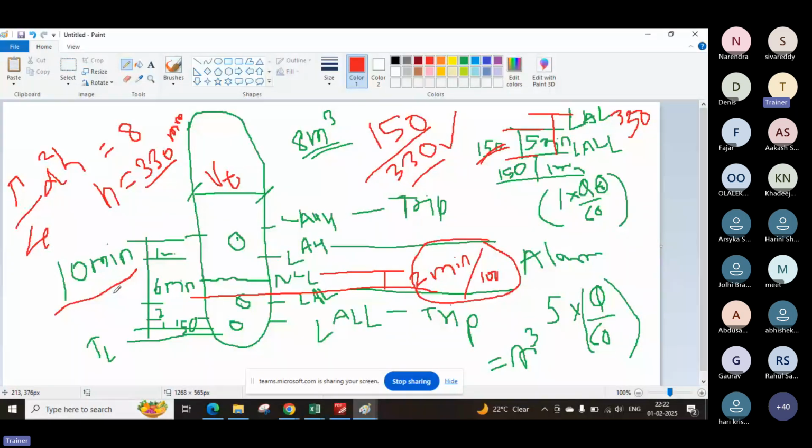Now you're talking about the earlier question, like how we define this liquid level. We keep this liquid level the same between NLL, HLL, and everything. But generally, people keep some margin between NLL to HLL and NLL to LLL, so that any upset will take sufficient time to reflect in the system, and there shall not be any spurious trips all the time.